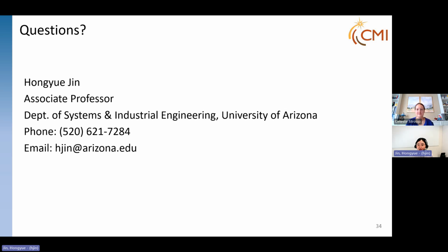There are some variations that, like dynamic version of the Aspen, will look into the startup and phase out, but mostly on the steady state, and we give the software some input on what would be the reaction efficiency, 95% based on experimental data or literature data, and what is the reasonable time. We provide the software this information, and if there are some errors, they will prevent us from running it, and then we go back and check what was the problem. Hopefully that answers your question, Scott.